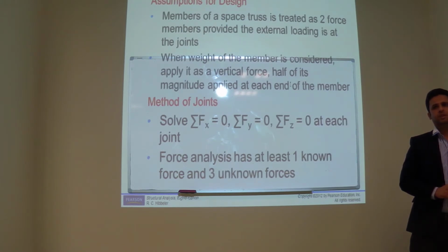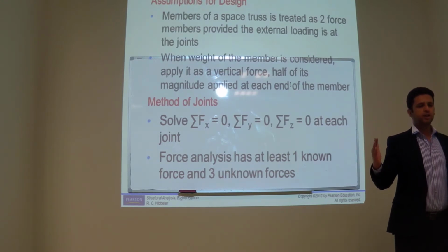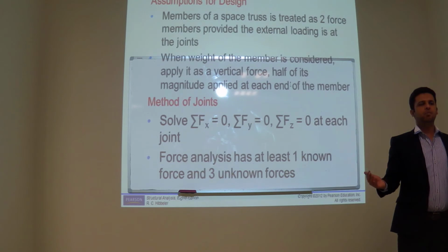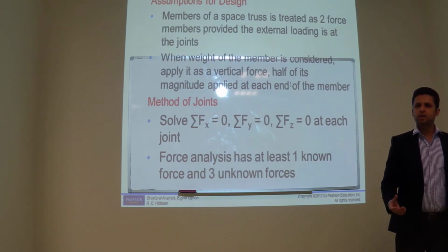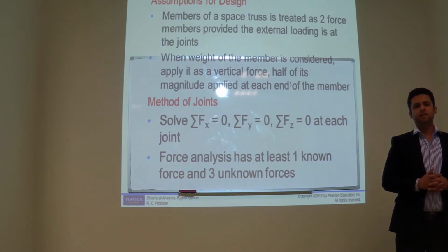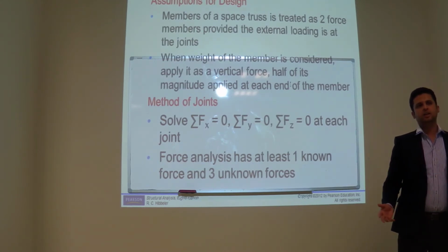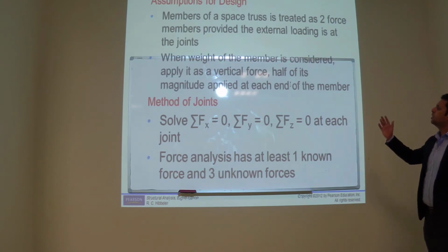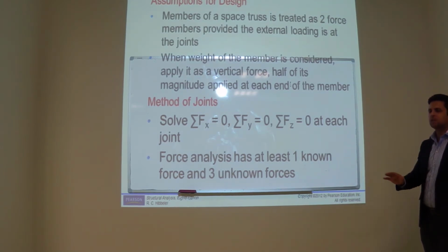Design what? Your assumptions, because during your design you assume that these two joints will be fixed. But when you have provided the hinge joint, then it will be different. It will not be a correct design. So whatever you assume, you have to provide in the real design or the real construction, using the same idea or the same concept.